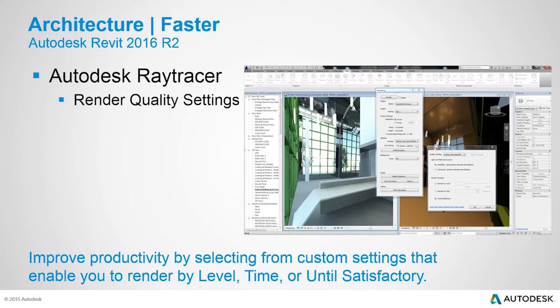And with this last feature, you can see how the rendering is progressing, and there's a dialog box with detailed progress information about your rendering. Depending on how much time you've got available, you may not know. You've got to get something out of the door. You can start it rendering to get the best quality you can, and you can leave it right up until the final hour before you say, that's good enough, we'll stop it, let's save that, and we'll use that in our presentation. So this improved render quality settings is a very nice one as well.